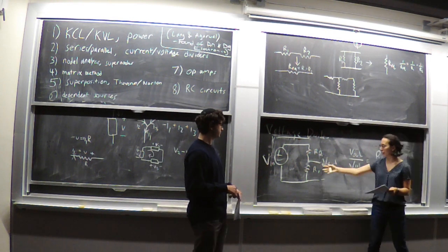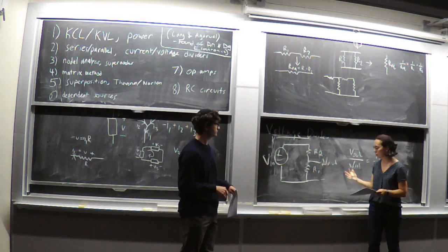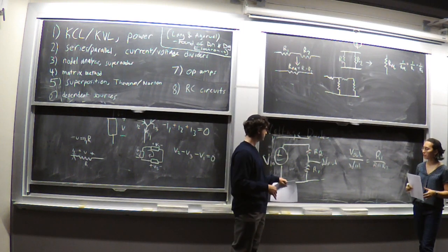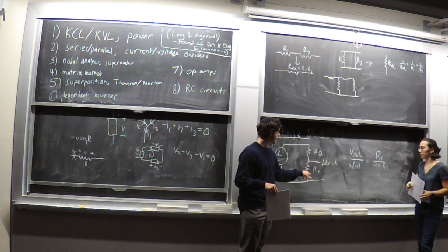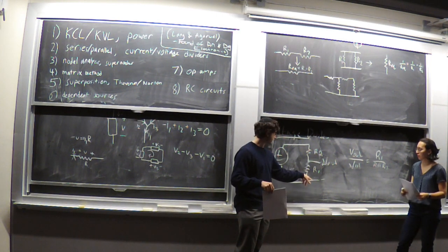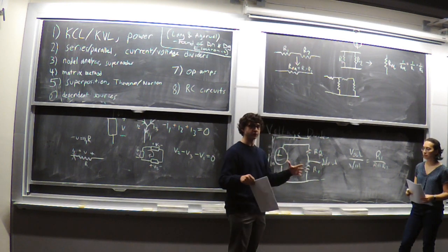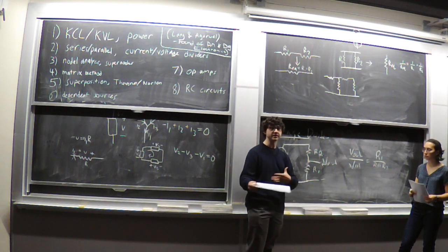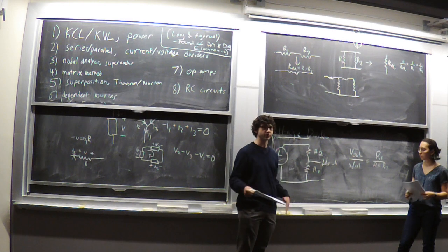So always commit this to memory. You should not have to apply any techniques to solve this problem. You should know it by heart. Two somewhat subtle things that are important to keep in mind here are, one, as Hannah drew, first this was just V out. You have to add this other terminal here or define a node as the negative side, because voltage is a differential reading, and so just saying that this is V out, it's V out relative to what? You always have to have your relative reading, and so that's when we define a ground node, which we'll get to in a minute. That's just always the universal zero for the circuit.